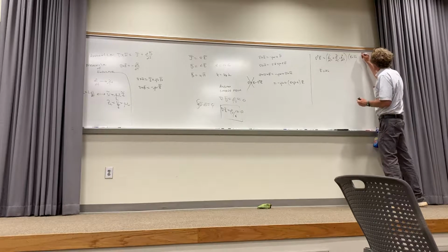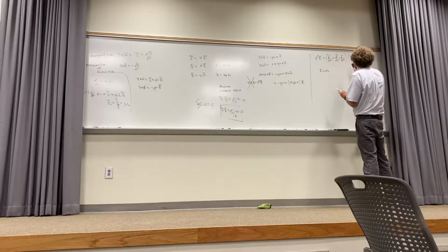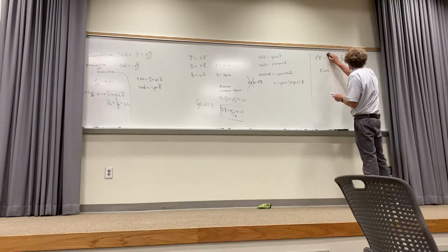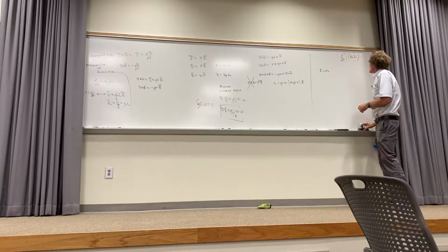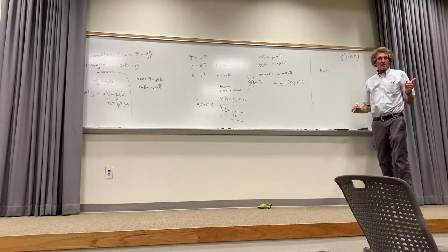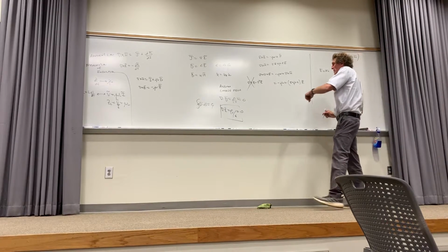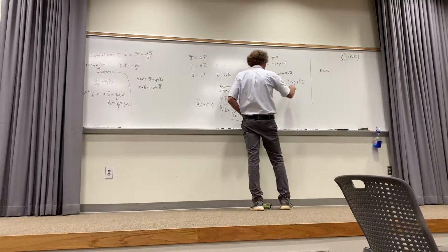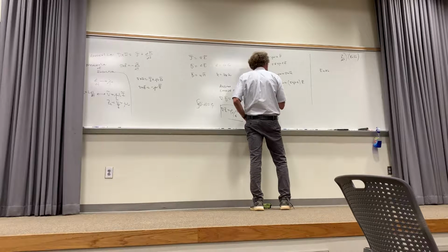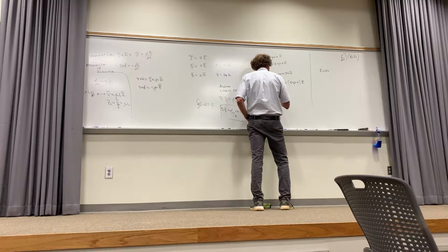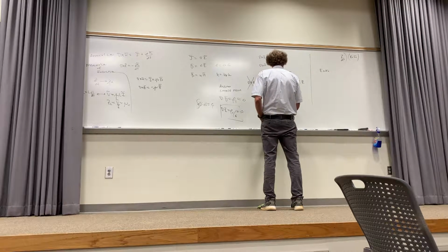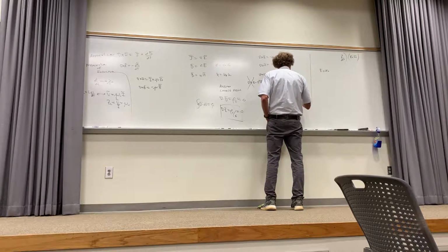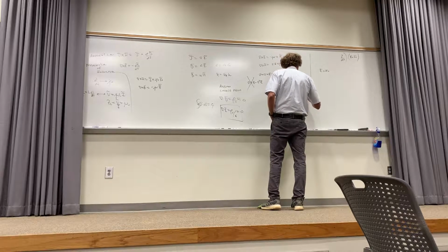This is really what we have going on right here. That del squared operator is just going to be the second derivative of Ex with respect to z squared. You follow me? So this del squared operator here becomes, I'm going to take the del squared and move it to the other side. So it's going to be the second derivative of Ex with respect to z squared. And now it's got to have minus j omega mu times sigma plus j omega epsilon times E.